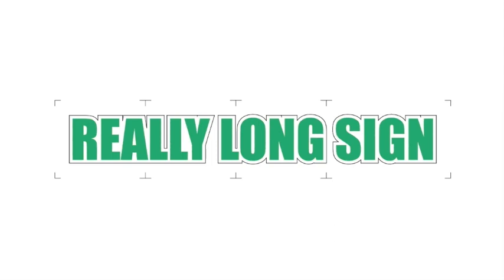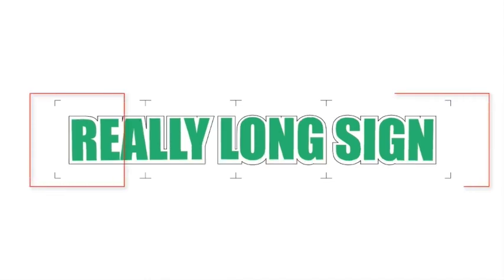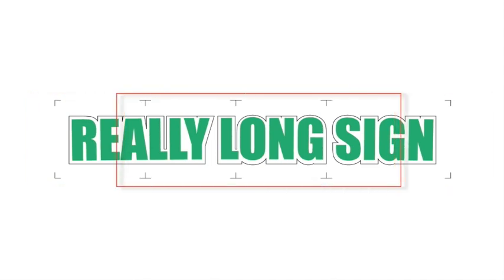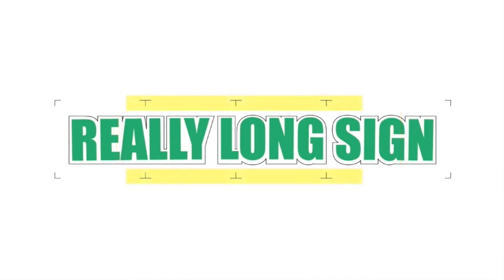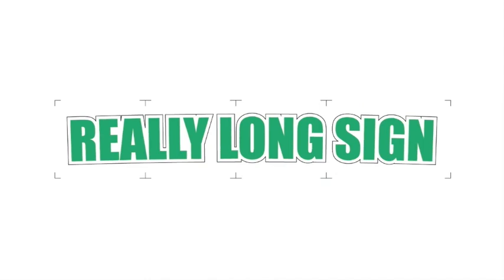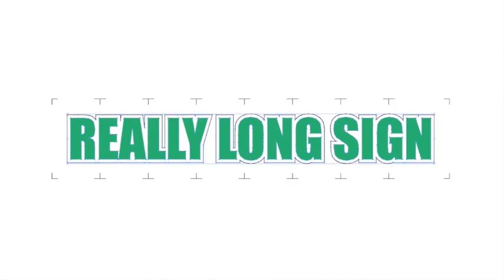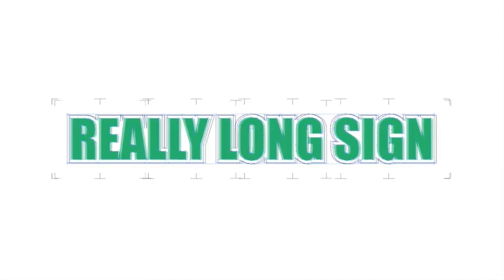In a print like this, if only the four corners were scanned for, you might find that the beginning and the end of the printed image are cut accurately, but the midsection would be a little off. On the other hand, when reading these registration marks, the cutter can adjust the cut line to compensate for the shifting. When choosing a pattern, keep in mind that more segmented registration marks ensure better accuracy.